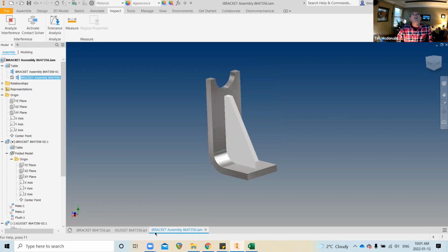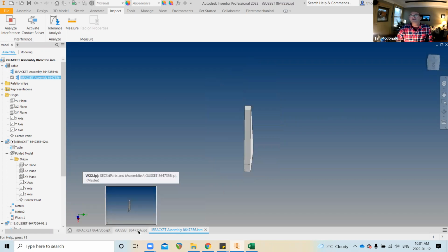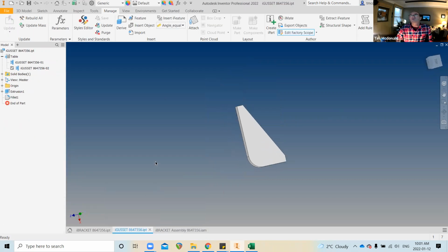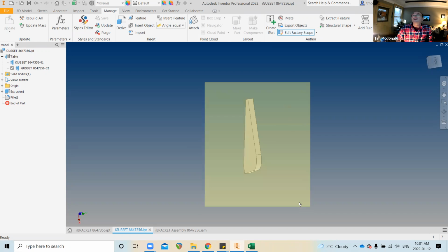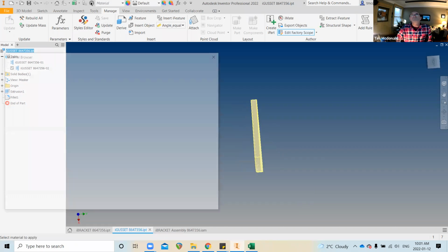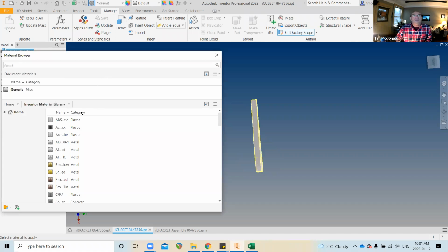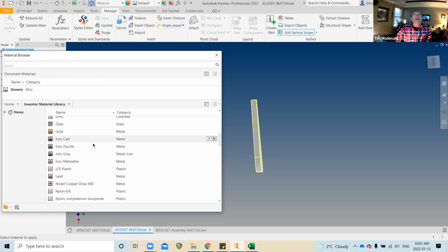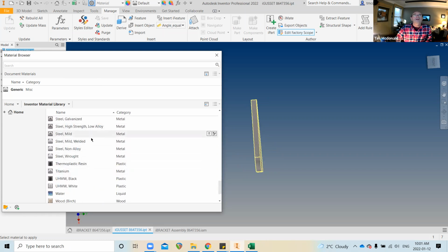Good point. Let's go back to the gusset. Let's assign our material right now. I've selected the component. Basically, well, I only selected one face. Selecting the entire component, you can come up here and pick material. And this window has never come up right. Let's go down here and let's make this the same material. That just makes it easier for the welder.